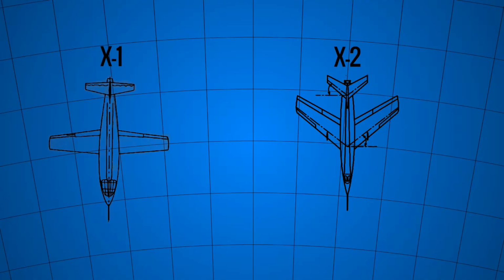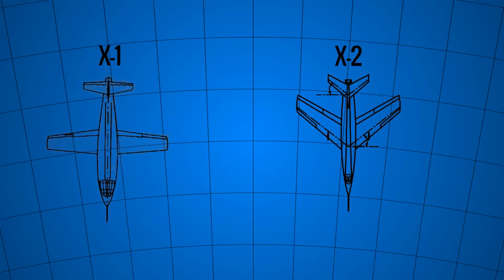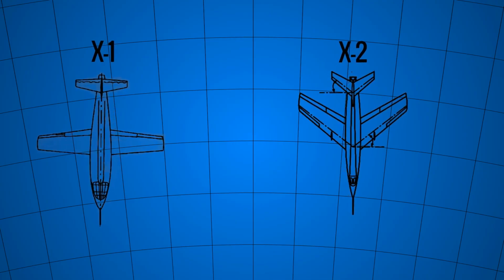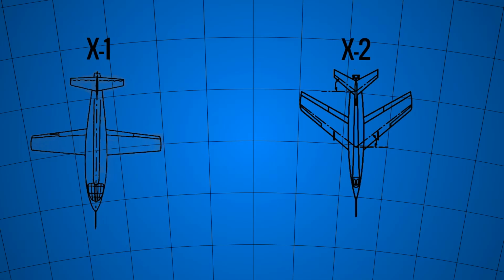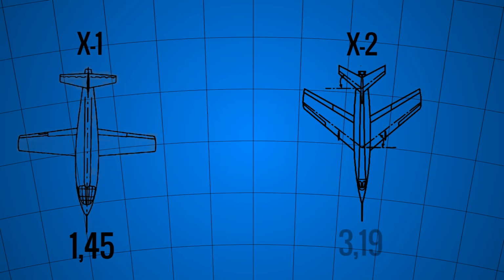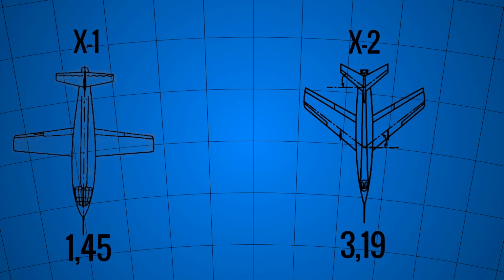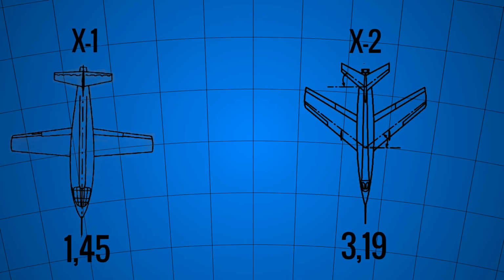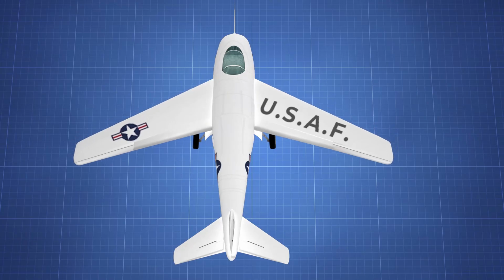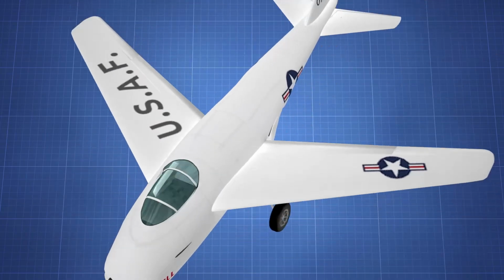But when it approached transonic speeds, when it was going at Mach 0.90 something, the plane started to shake in an incredible way. In fact, it managed to fly at supersonic speeds, but it didn't go much above Mach 1. However, the X-2, the older brother, flew up to Mach 3. You don't have to be very smart to notice that the X-1 has straight wings, however the X-2 has swept wings. Let's see why. What we have here is an X-5 plane, capable of changing the wing geometry in mid-flight. It was the first experimental plane capable of this.